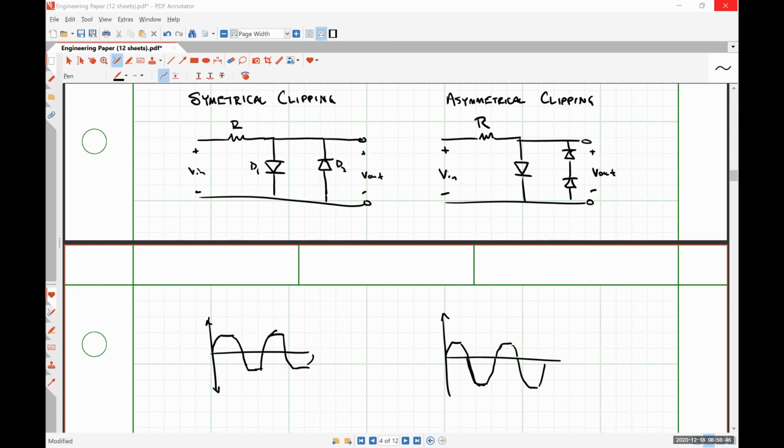That is because if you choose a diode off of a sheet and you're regularly exceeding the maximum reverse bias breakdown voltage, you can't assume that diode is going to work how you think it's working, because you're effectively burning it out if it's an avalanche diode. And then finally, do a SPICE simulation of all that kind of good stuff.